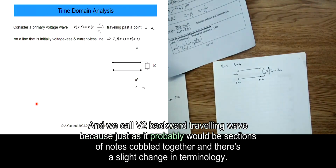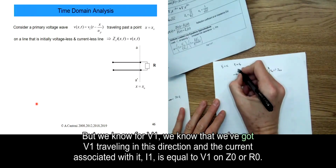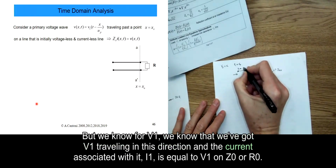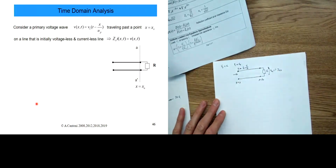It's just that the notes were probably cobbled together from different sections, so there's a slight change in terminology. But we know for V1 that it's travelling in this direction, and the current associated with it, I1, is equal to V1 on Z0, or R0.